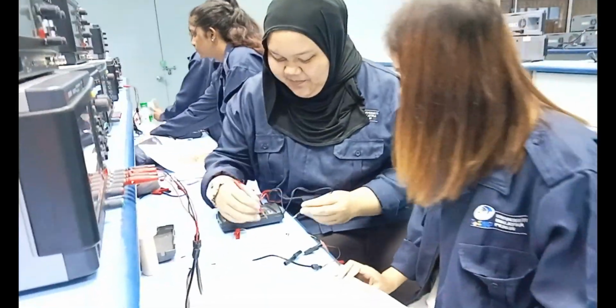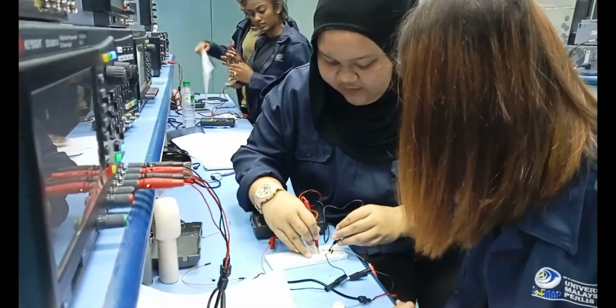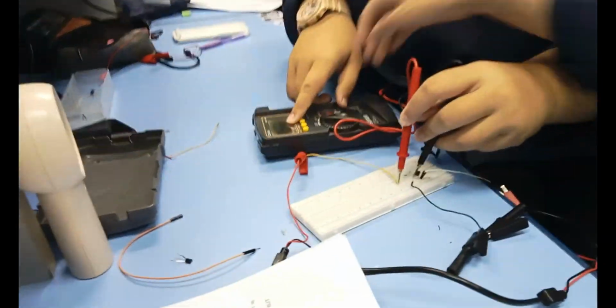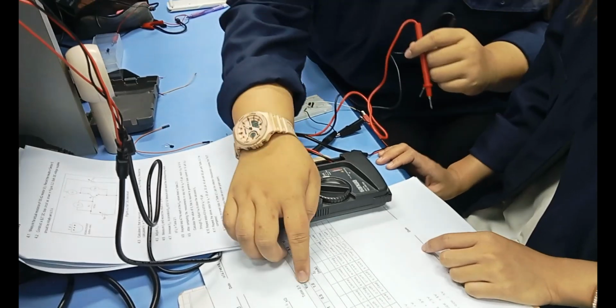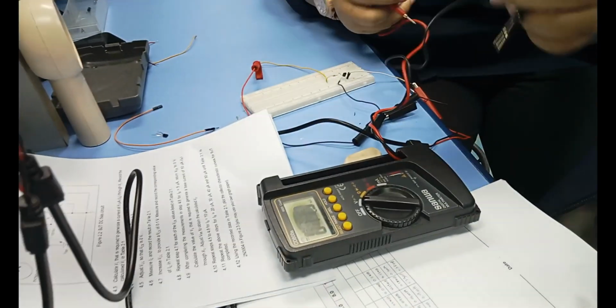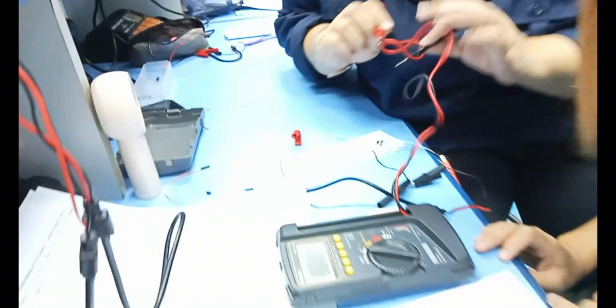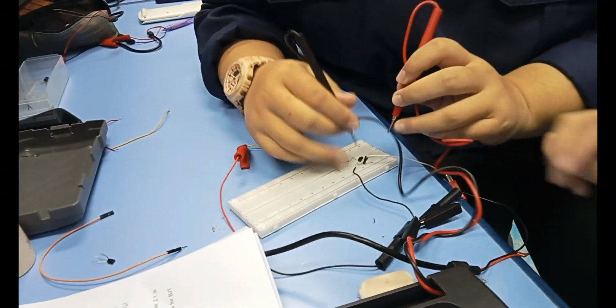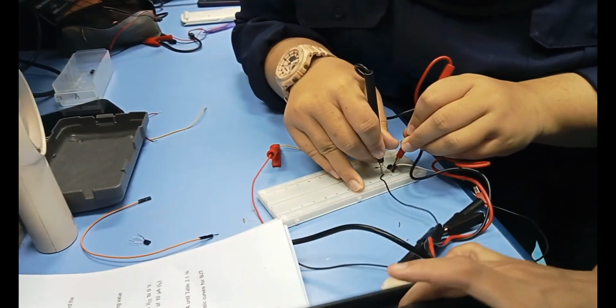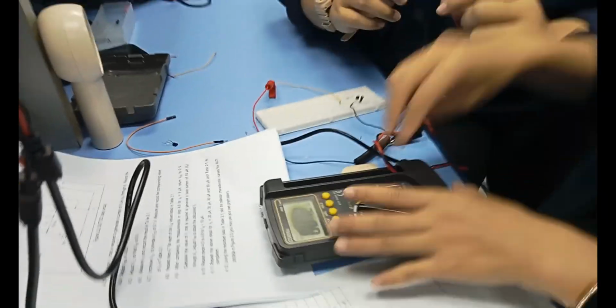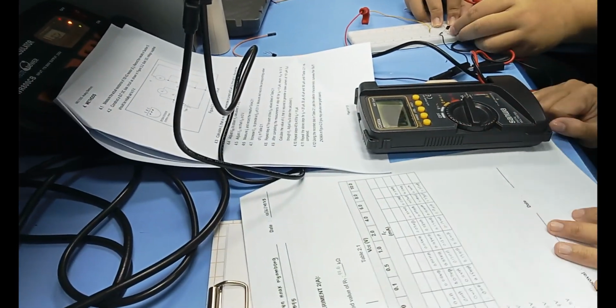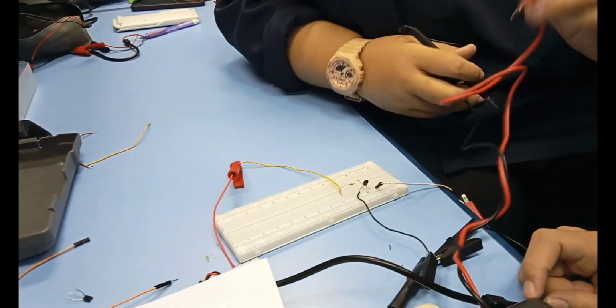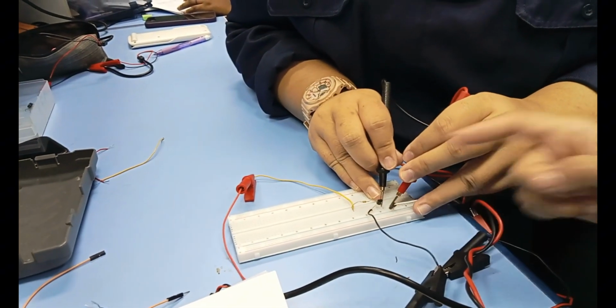Okay. We put the current one. So here we get 5 volts from V1. So we got V1 at 5 volts. So we want to find IC. So for IC from VCE, we use the multimeter. For example we take from 8 volts. 8 volts in. So measure VCE first. VCE here and here. So we get 8 volts. So after getting 8 volts here, then we find IC. Remove it here. Then connect the multimeter with the collector.